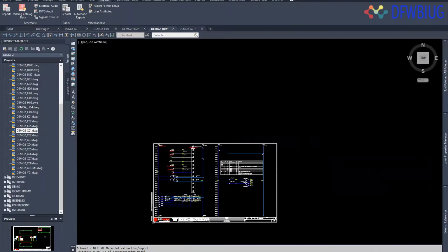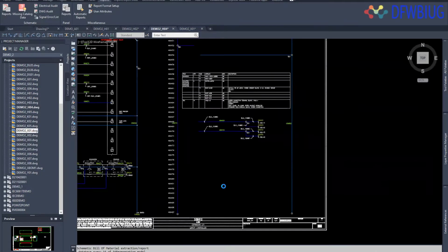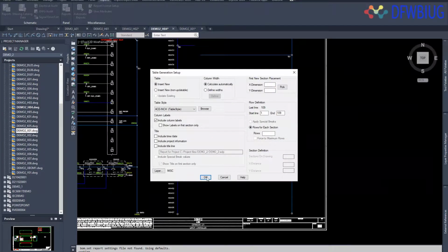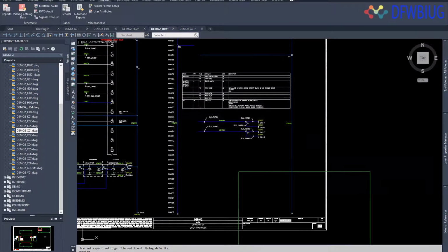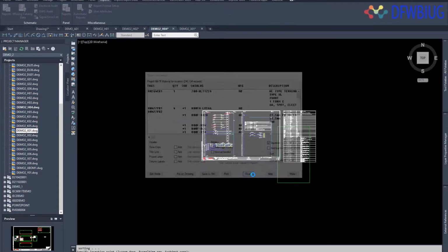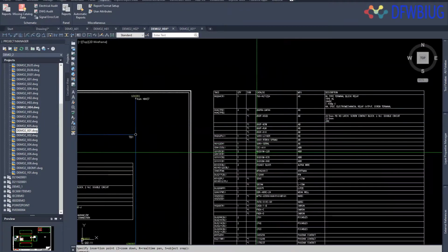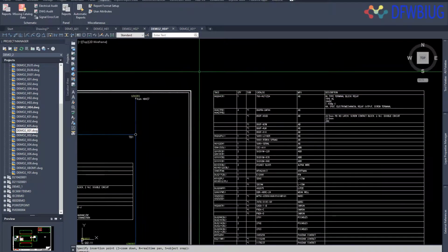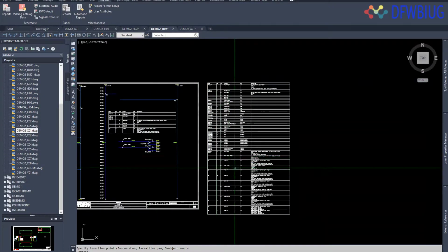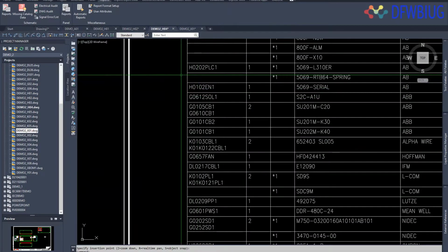The idea is basically that we are searching for components which I've specified are in one place. Now, when I put this bill of materials together, I will be able to break down by location what schematic devices I have, which breaks down into what I have for a panel location by device.